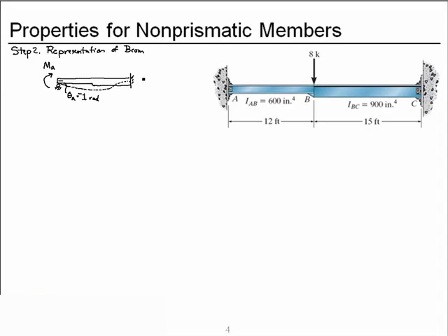And then we're also looking for the moment created at the other side when M_A is applied, and we'll identify it by the carryover factor times that moment. So there is a moment generated here, and we'll express it as the moment at the left and whatever carryover factor is required to convert this moment to the combination we would calculate here. And now I'm ready for step 3. Superposition of moments.